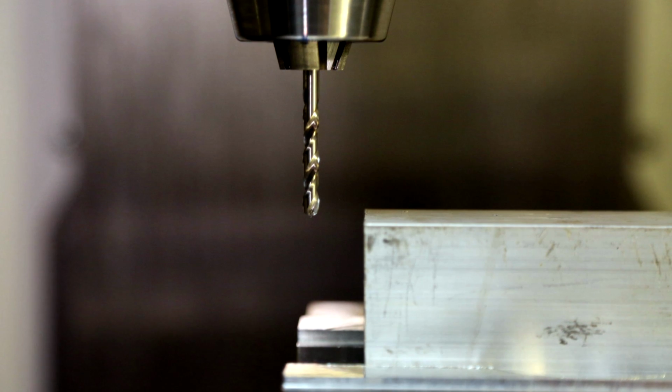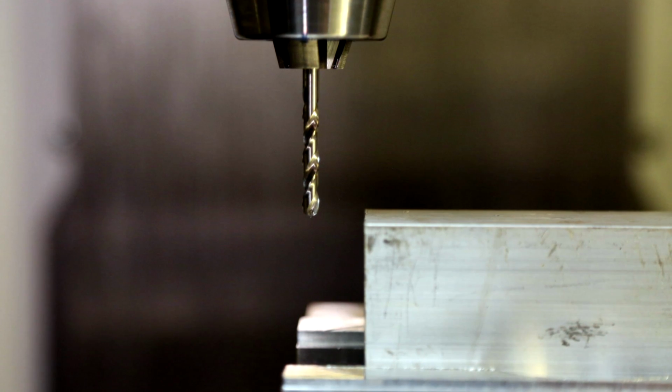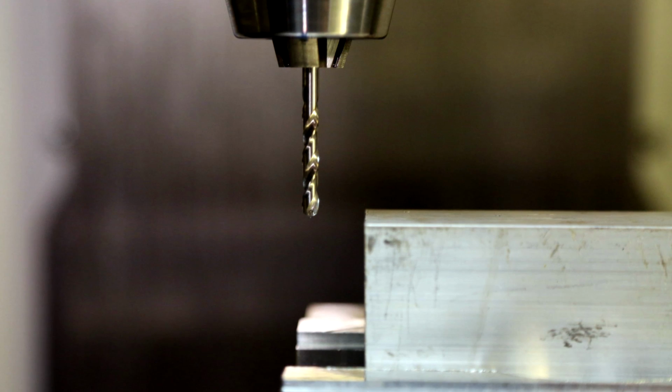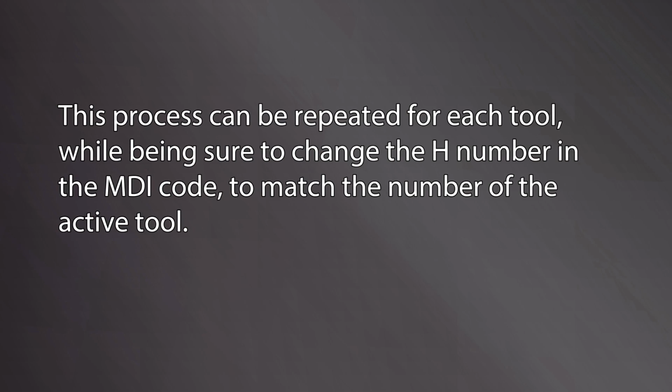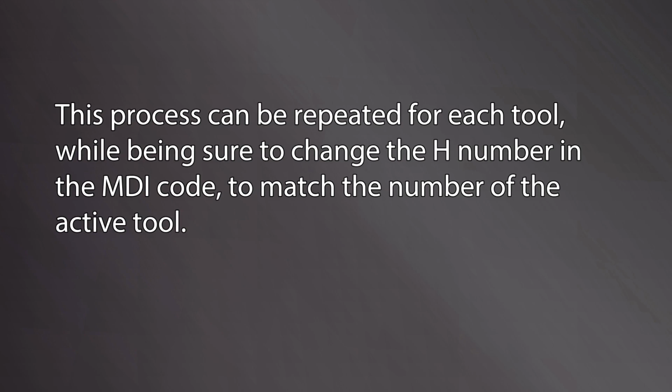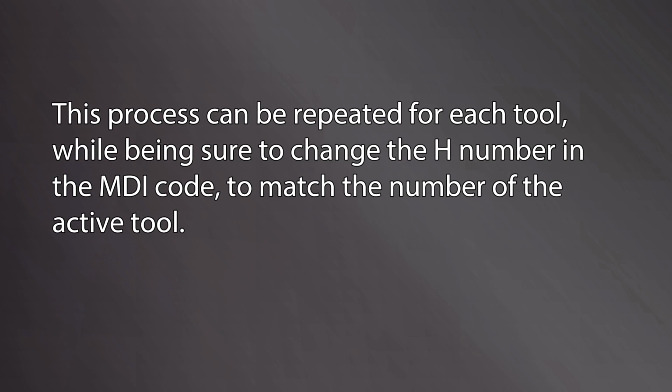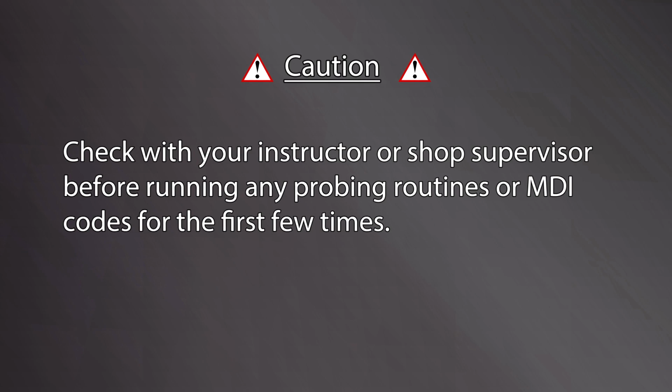We have now completed visually verifying our Z work offset and one of our tool offsets. This process can be repeated for each tool, while being sure to change the H number in the MDI code to match the number of the active tool.